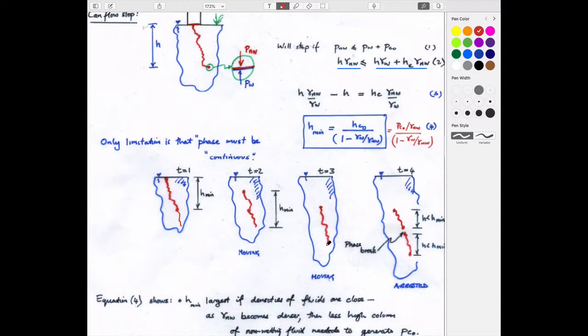And you could imagine two ways why it would stop. One is that it could hit something here that has a higher entry pressure, has a smaller pore space, and so it can't get in, in which case it would stop, and maybe it would puddle on this. It would just go on top of it like a puddle on top of this.